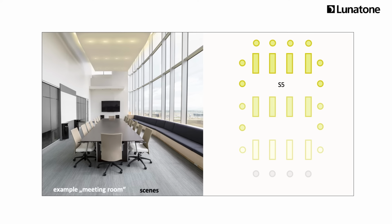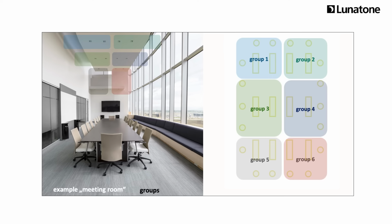DALI is very flexible. If these light settings need adjustment, it can be easily done with software. No structural changes will be necessary, and definitely no rewiring. The groups and scenes can be easily reprogrammed to fit new requirements.